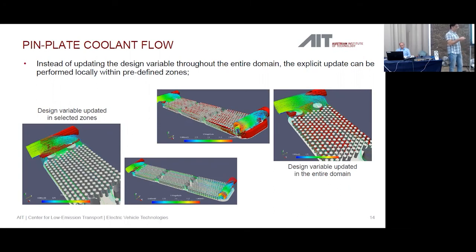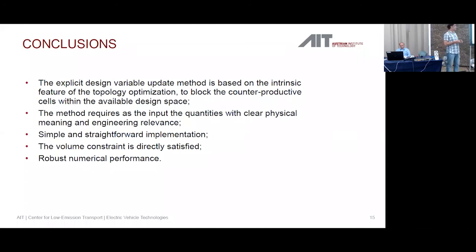I can set a zone and say, yes, only sensitivities in this region are used, and the design variable field is updated. So this is more or less the idea. Very simple, but a very long way to say it. I used for my topology optimization only those parts that I somehow handpick through the parameter which does make physical sense. I want 5% of this volume here to be filled with some sand in order to get, in this example, power